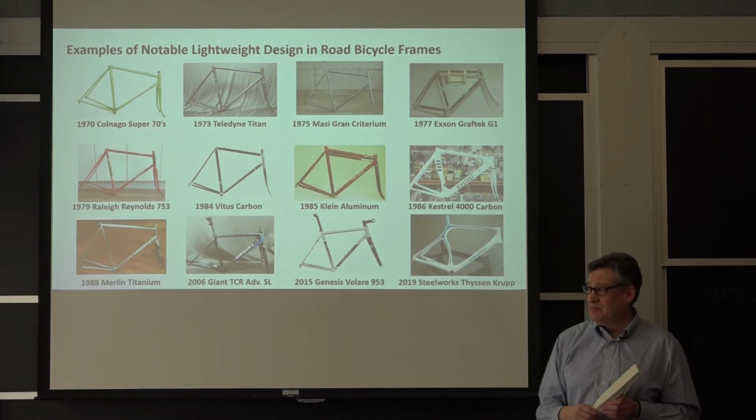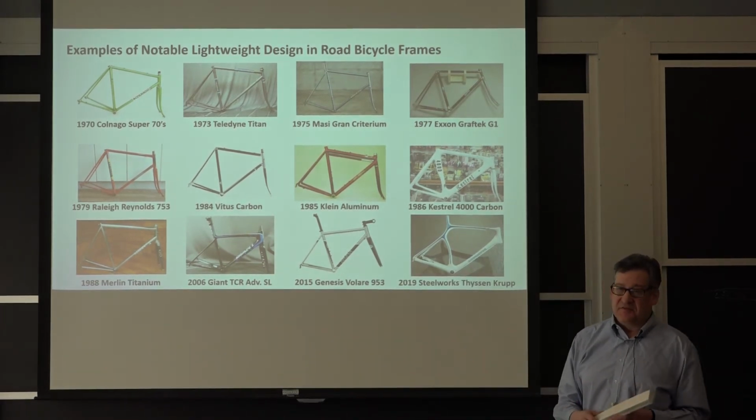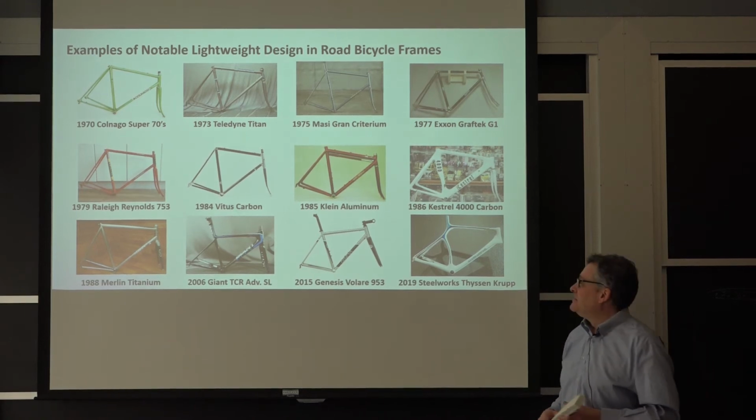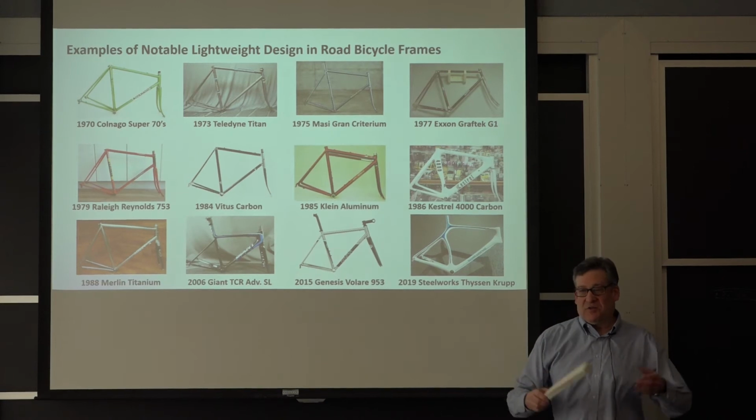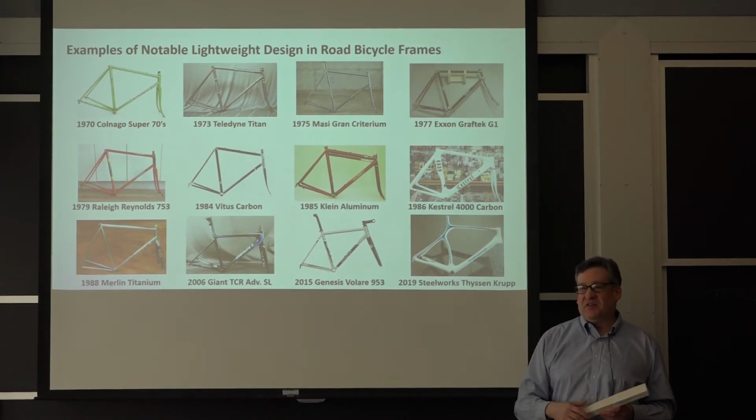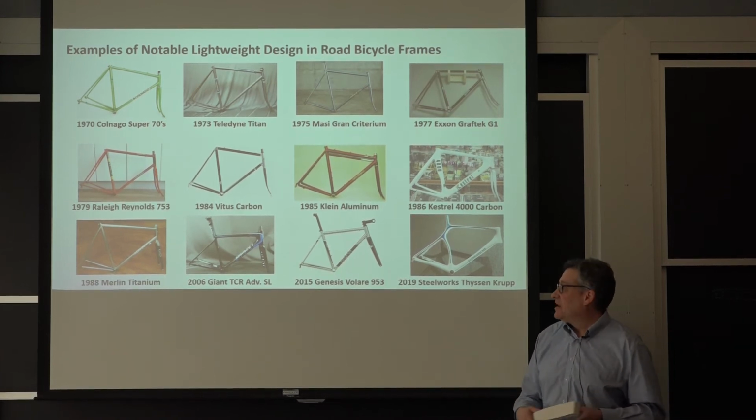They apparently last forever because of the fatigue resistance of titanium, right? It's better than aluminum. That's sort of the idea. It's for stiffness, and the idea is that you want to lower the stress low enough so that there are enough cycles left in the frame that it'll last at least your lifetime. I think it usually works too.